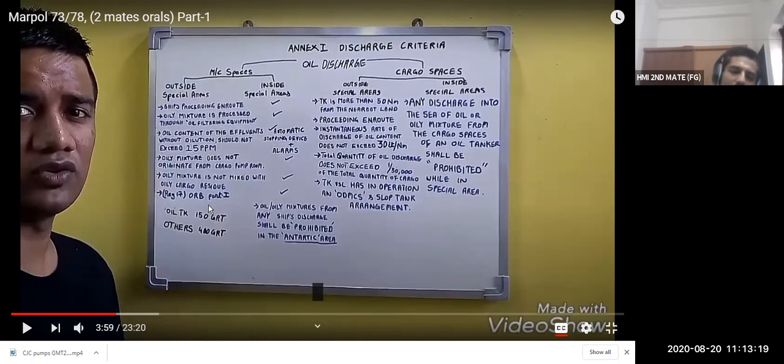Part 1 will have bunkering, lube oils, gas oil, diesel oil, consumption, internal transfer, ballasting, cleaning, sludge tank ROB and landing reports. All will be in your ORB part 1, generally signed by the chief engineer. Every entry is done by the chief engineer.